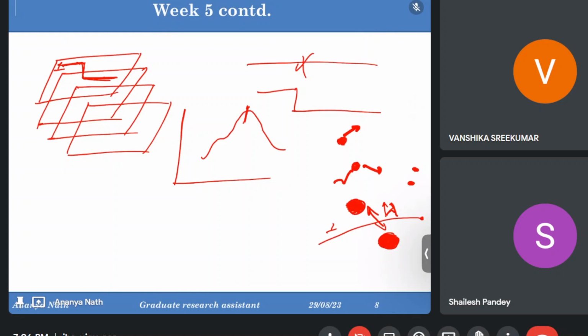Due to the cold working, there can be some alignment of the grains, some stretching of the grains, but we cannot really play with the solute atoms. This is why we have taken help of the dislocation. There we were trying to move the solute atoms and make it bigger. But here we are trying to get the dislocations together and make a bigger dislocation: pile up, multiplication, this forest thing, cellular structure. When a lot of dislocations have piled up, they will make the cellular grain structures.